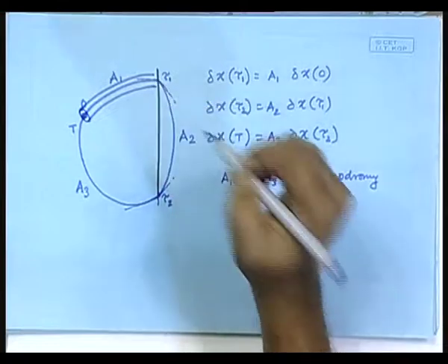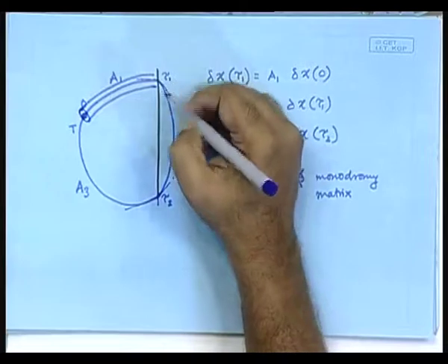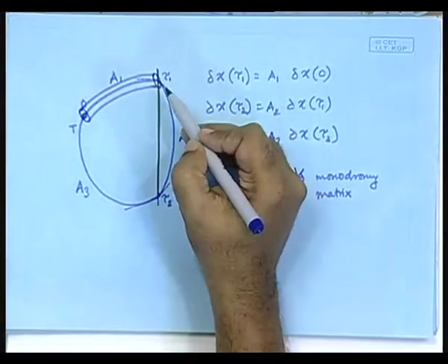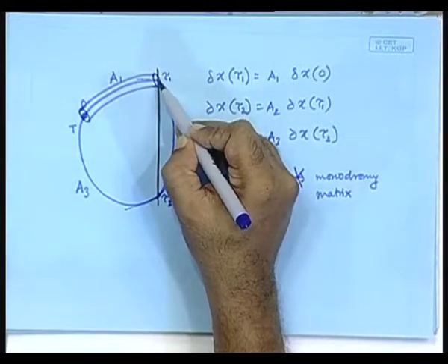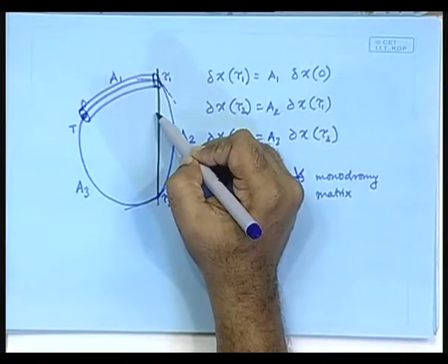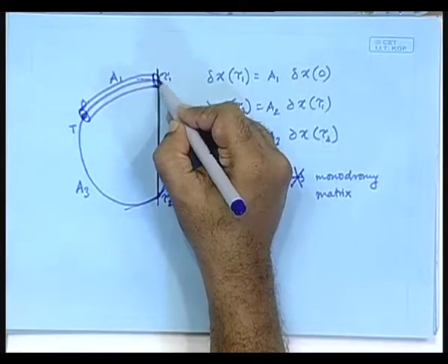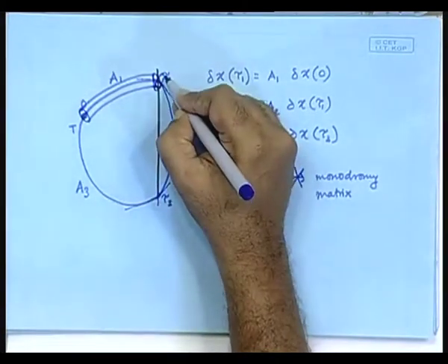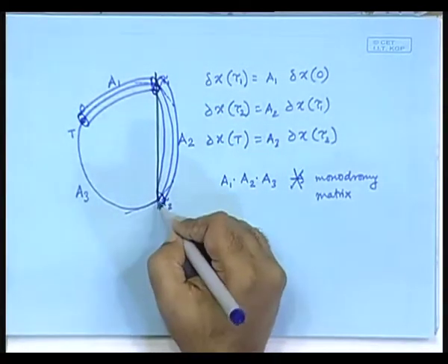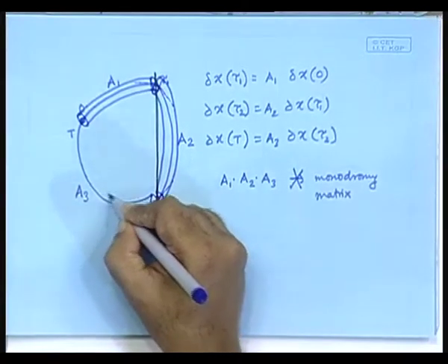And then at this point, the original trajectory reaches the switching manifold, and the perturbation is something like this. But then after it starts, you see that all the points on the perturbation do not reach the switching manifold at the same time, they reach at different times, and therefore, after the perturbation you start from a different ellipse, and then you go on coming to this and you get an ellipse. Here also you have some kind of a different ellipse to start with, and then that goes on.